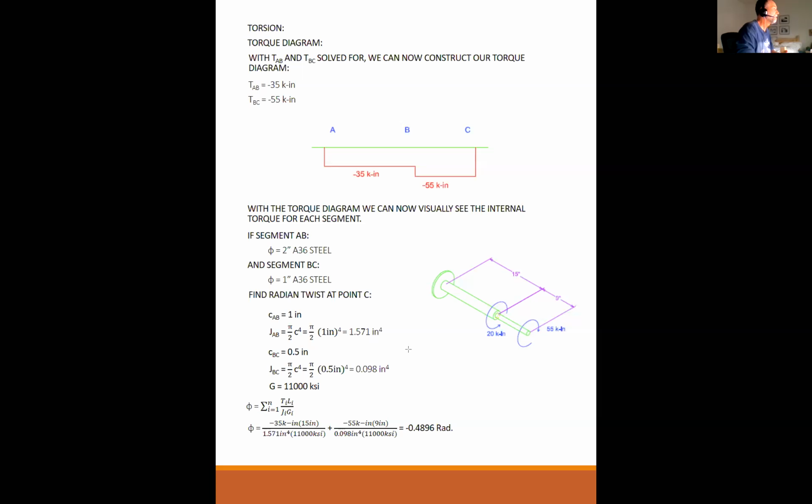Any other questions about this? That was a very good point, though. That was an excellent question, that the axially loaded members that we talked about before cause normal stress and normal strain. Normal stress is 90 degrees out of plane with shearing stress. So the shearing stress can happen or not happen totally independent of the normal stress.